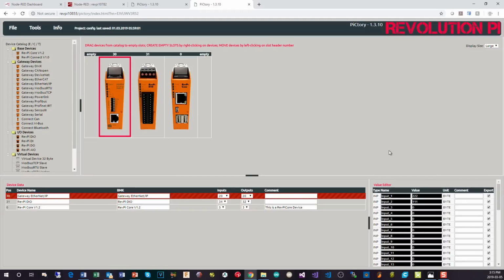And the way that this works is that it actually overlays the coils and the registers on top of each other. So if you're using it in binary mode, say we've got one input here that is a byte. These two together, in Modbus, would have input 1 and input 2 combined. That would also be 16 bits. You would just use a different offset in the command to set the bits, which means you can bit manipulate the word. As I said, I'm going to get into that in a whole other video. I don't want to dominate this with going through how this all works.